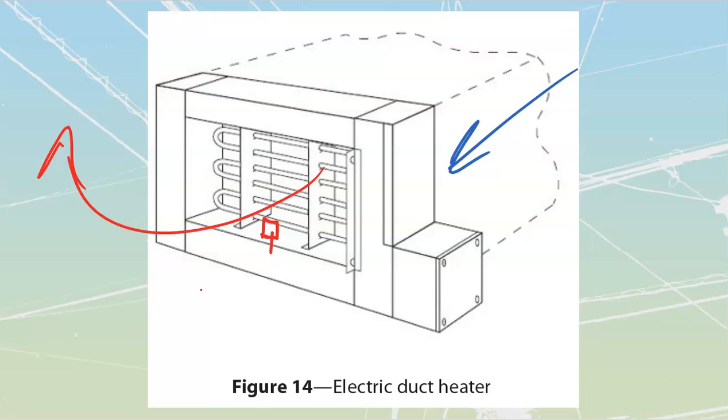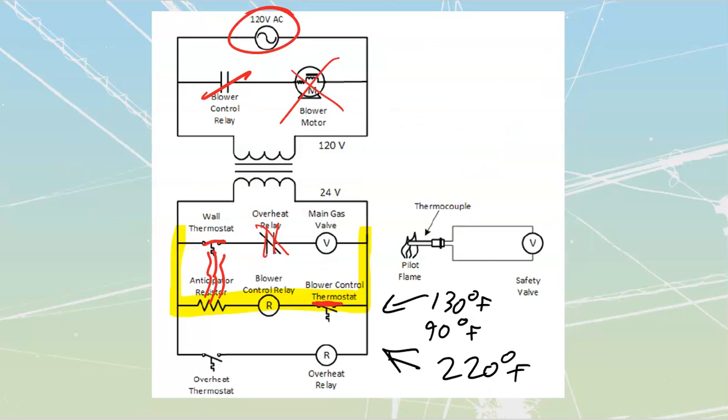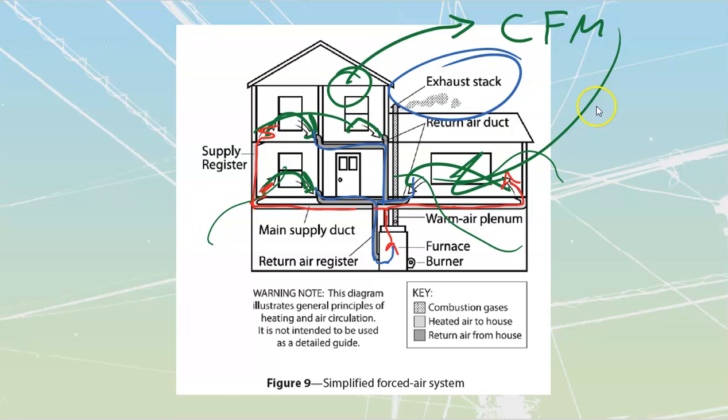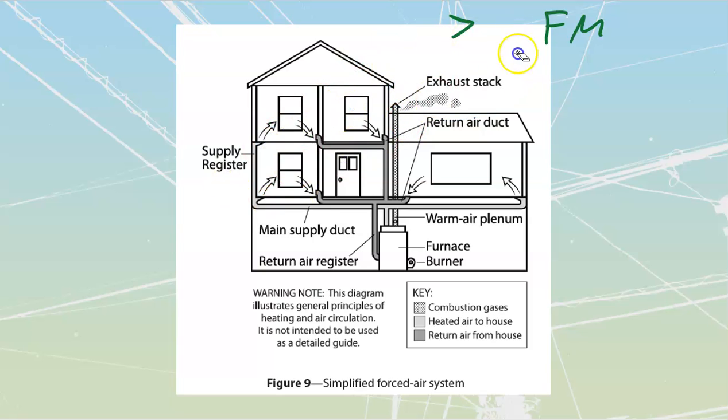Plenum heaters, last one that they talk about, is a less common one. Plenum heaters are going to be installed right above my furnace over here. So I'm just going to take this one. My plenum is going to be the heated section that's going to be up at the top over there. We stick them directly above a gas-fired furnace, and they're designed to work in tandem in places where we just can't keep up, particularly northern BC and a lot of our other provinces.